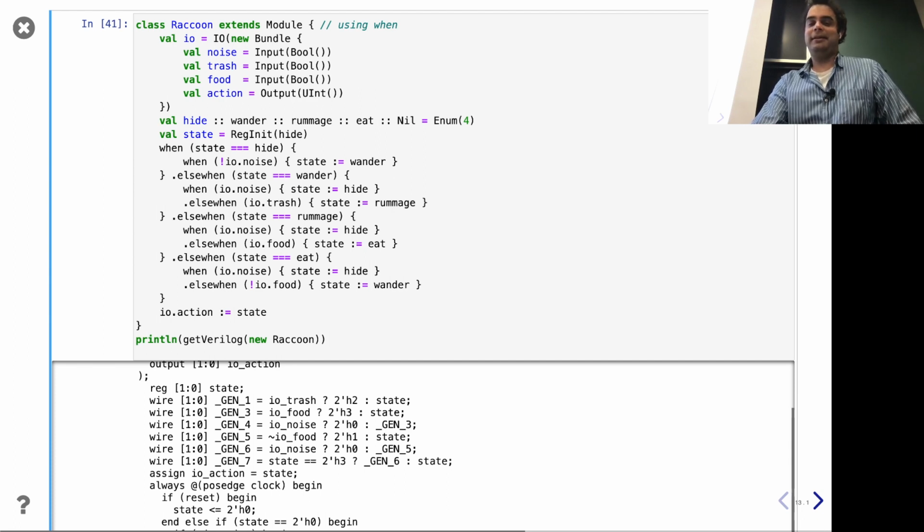That being said, there's actually a portion of one of the RISC-V processors that does run some things in Scala to try and determine the states on the fly. But in terms of default stuff built into the language, I'm not sure. Sometimes I'm okay saying, maybe it's a small efficiency hit if my 2-bit state machine doesn't have optimal state assignment, but I'll live with it. The important thing is to get things that work.